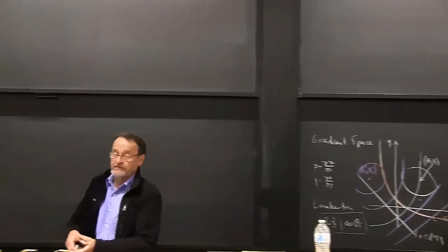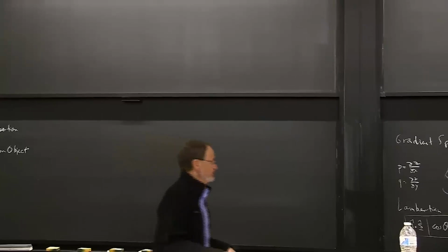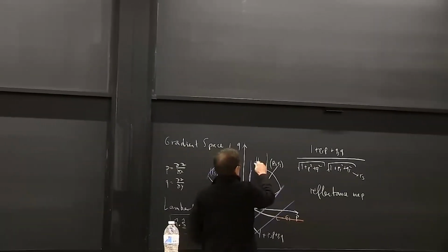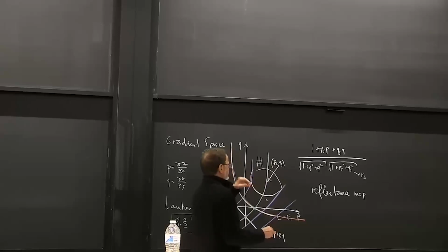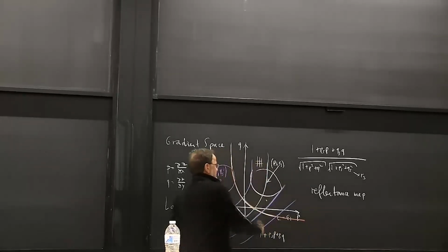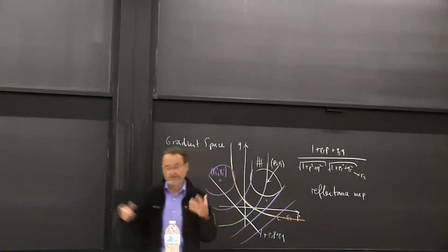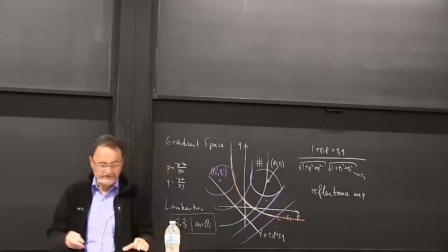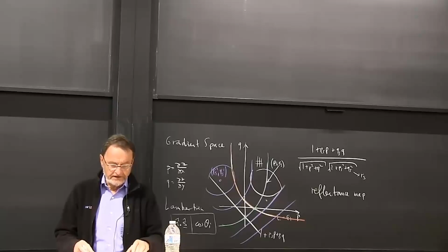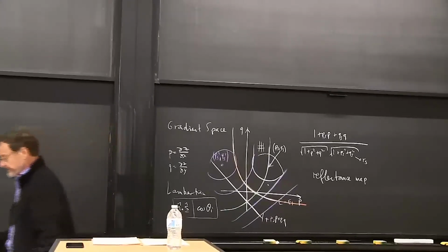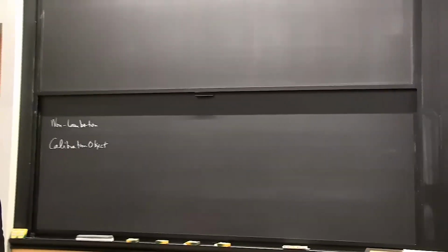It's going to get pretty tedious because you have to basically explore this whole space. And every cell in the space in your lookup table is going to require that you reorient that piece. Now, of course, you can automate that and have some robot do the calibration for you. But an alternative that's often easier is to use a calibration object of known shape.